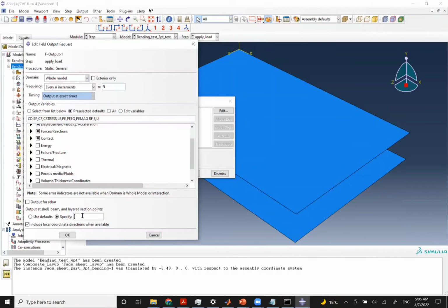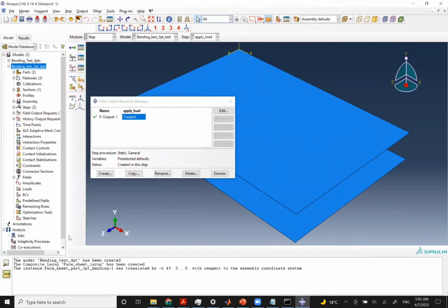And to do so, we select the second integration point, just like here we're saying we need 2. For the second layer, we move to the second layer of the second element. So we add 3 and 8 and 11. So that first layer, second layer, third layer, and fourth layer. And for all of them, we're taking the middle integration points. And okay,